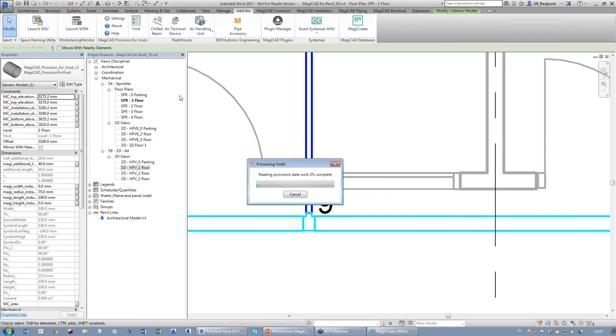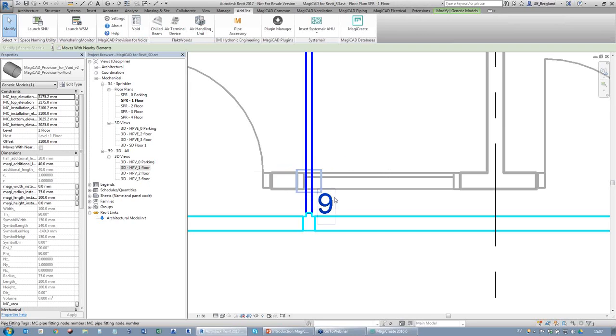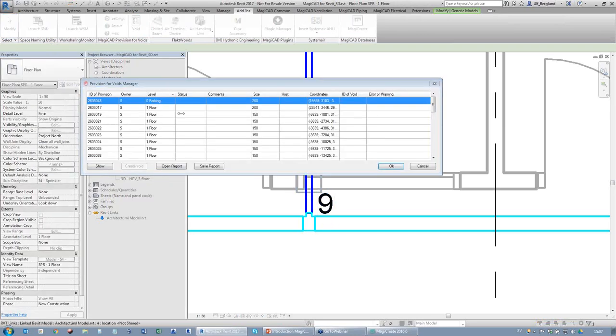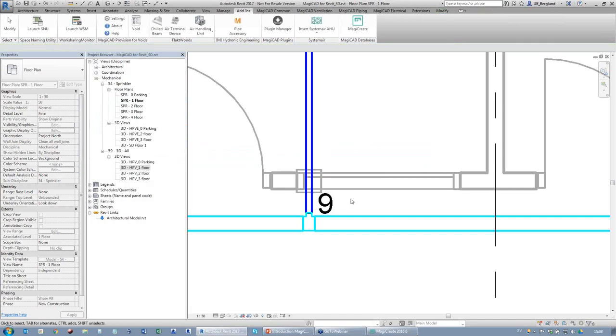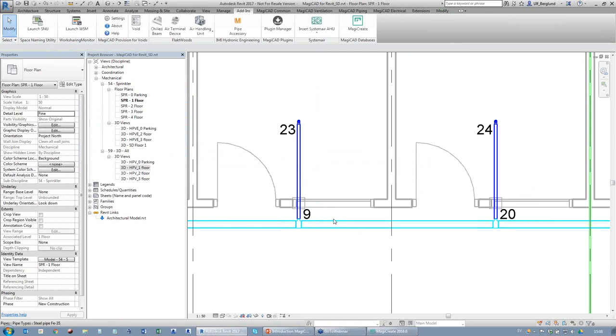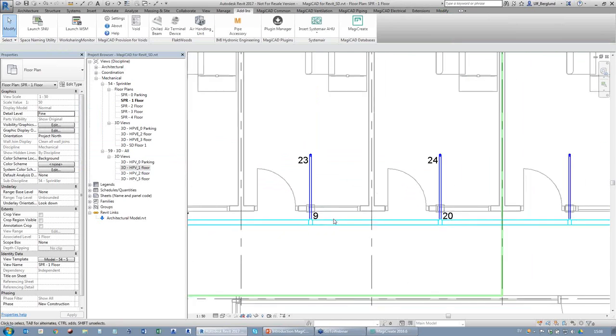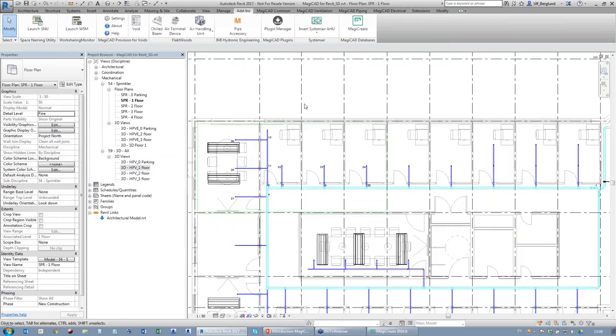And then when they run this void tool, it will sense all those voids, and they can create by just selecting the ones they want to create. And when they are in their model, they can just click this create void, and it will make that cutout physically into that wall. And then when we take it back into Revit here, we can see that when we make collision control, for instance, it will not find any collisions.